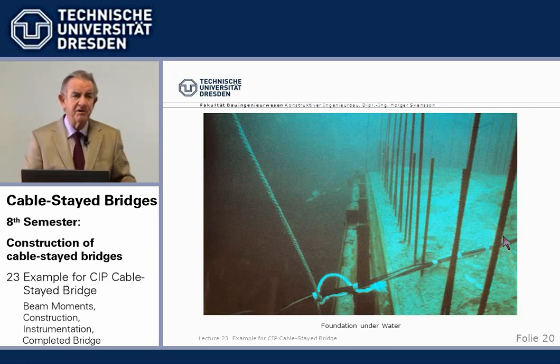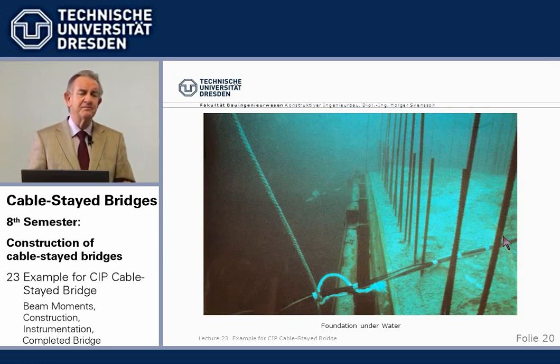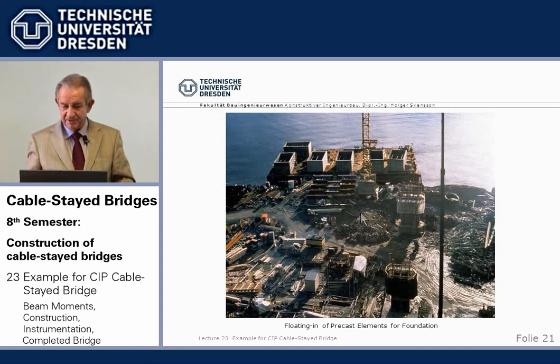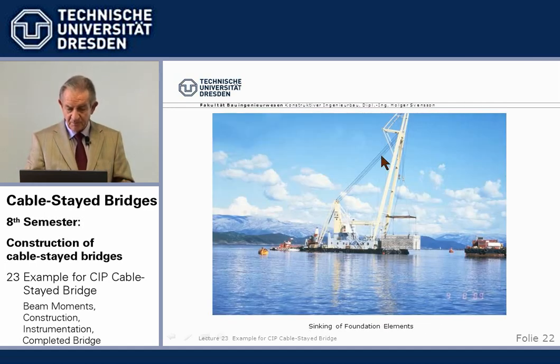I was always impressed, the civil servants who overlooked the construction there, they went down, one or two of them, in diving gear to inspect the underwater concrete themselves, and it was cold, but they were divers apparently, so they went down. Then the tower legs were built from precast boxes on shore, shipped to the site, lowered down with a floating crane onto this base, stressed together.